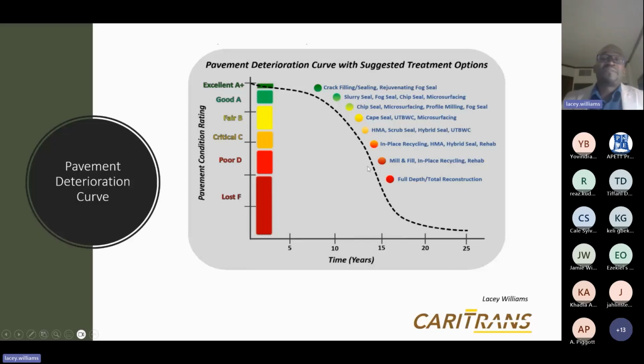And so you end up in something that is really unpalatable to everyone: the road user, the client, the taxpayer, everybody. So with the non-destructive testing instruments that are available on the market, if you were to capture deterioration as it starts up here, look at the remedial action that is required. Crack filling, maybe some chip sealing, fog sealing, but essentially solutions that are in the 4 to 5 digit region.